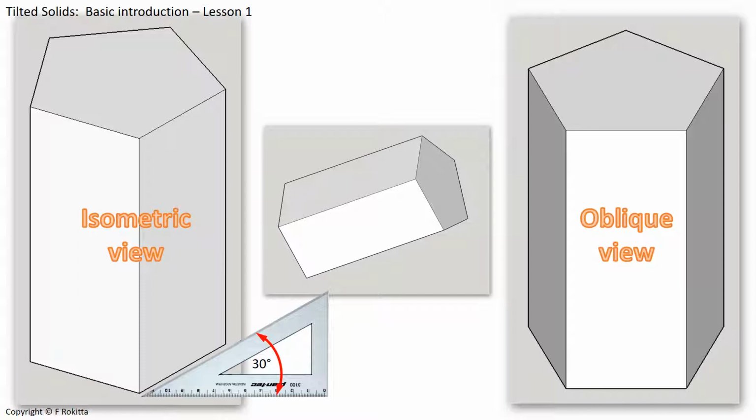If you draw the isometric view of the pentagonal prism, you will understand that the base of the pentagonal prism is at an angle of 30 degrees, as shown in the illustration. The oblique view's base angle will rest on a 0-degree base, and then the slanted surfaces could be at any other angle, which can range from 45 degrees, 60 degrees, 75 degrees, or any other required angle.